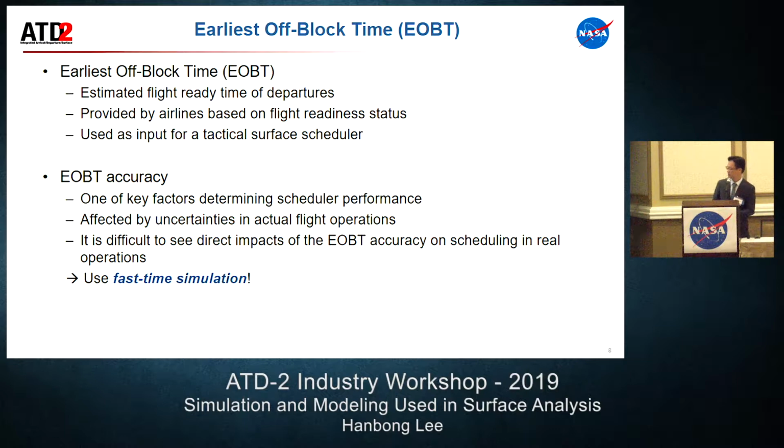But the EOBT data is not exactly the same as the actual off-block time. Sometimes the EOBT is far from the actual pushback time because of lots of uncertainties related to the flight operations. But we want to know how the EOBT accuracy can impact the surface metering and the airport performance.